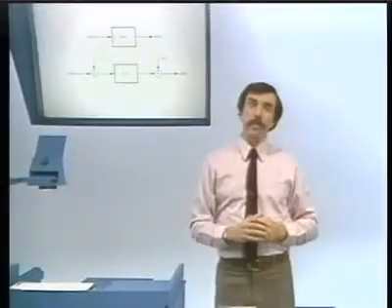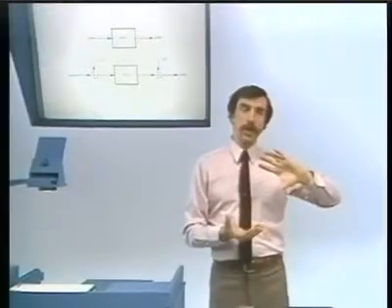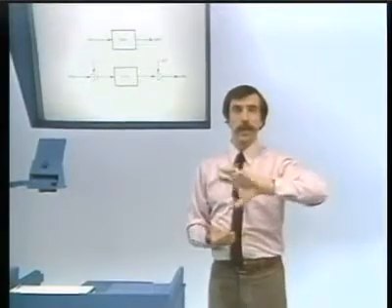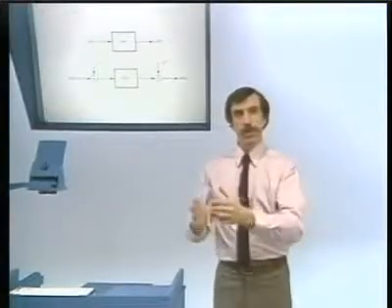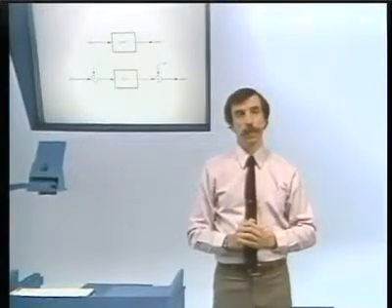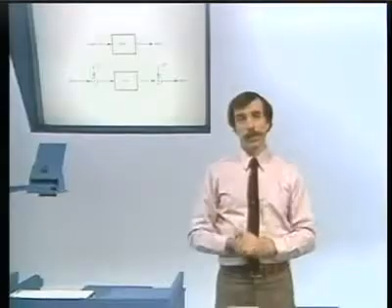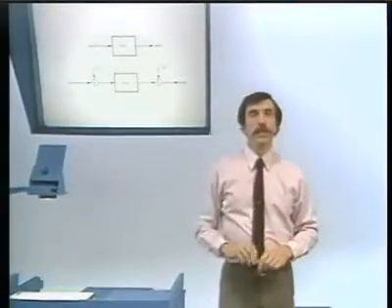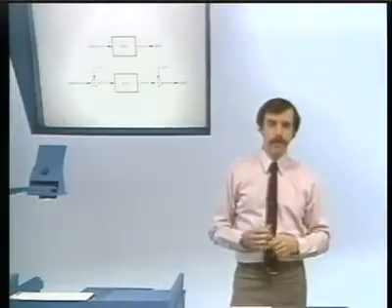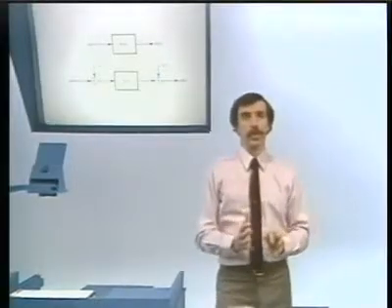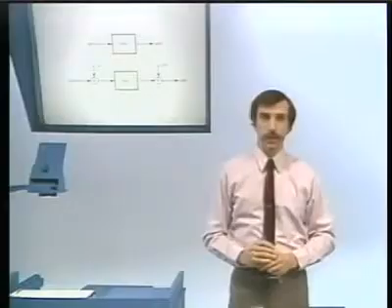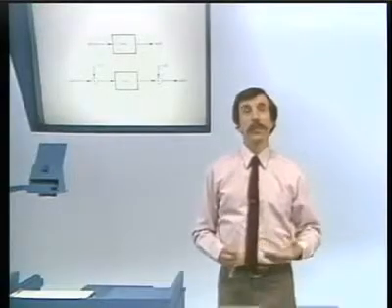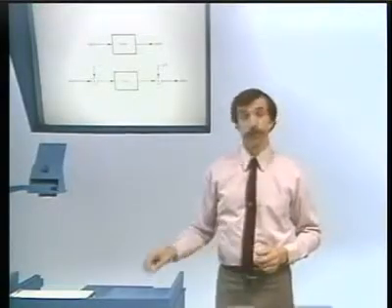The example that we happened to pick said if you multiply or modulate by -1 to the n, that takes low frequencies and shifts them to high frequencies. What that tells us as a practical and useful notion is the following. Suppose we have a system that we know is a low-pass filter, and it's a good low-pass filter. How might we use it as a high-pass filter?